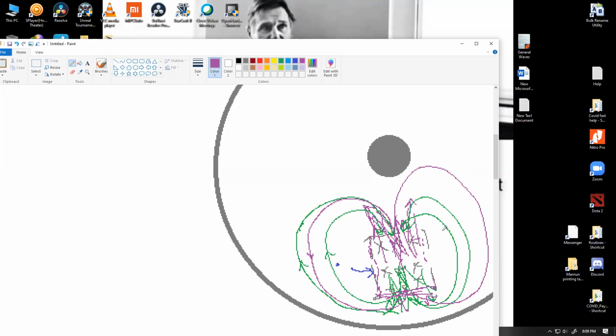As the electrons are made to move within the metal disk because of the magnetic field, they will produce some heating. That heat energy will be directly drawn from the kinetic energy of the wheel, which means if it is a high-speed metal disk and we introduce the magnetic field over here, this disk is going to start to slow down and heat up, which can work as a very good braking system for extremely high-speed vehicles. Because the higher the rotation of the disk is, the faster you can extract energy out of it.